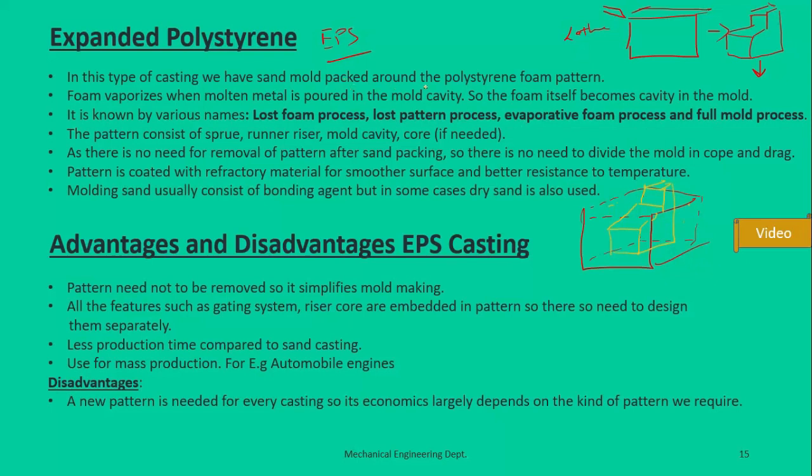We will pack the sand around the polystyrene foam pattern. We also machine the sprue and the runner within this foam pattern.